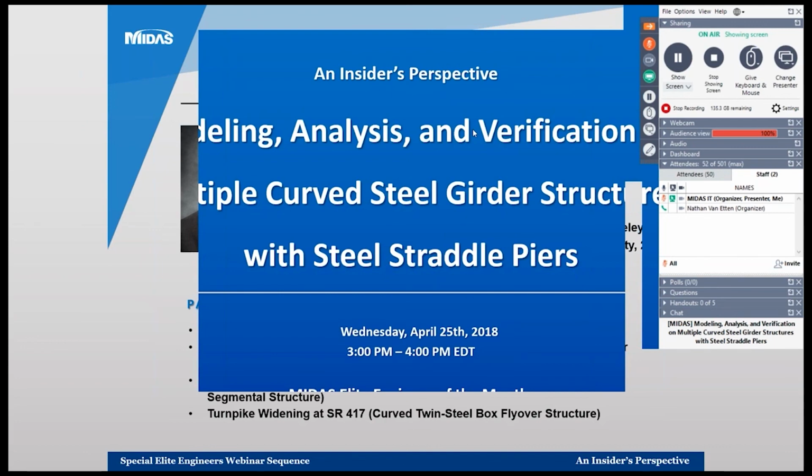When you have an elastomeric bearing pad, there's a lot of merit in accounting for that change in vertical stiffness, and MIDAS Civil can definitely handle that process. However, because in this case we're using disc bearings or pot bearings where the vertical displacement isn't very prevalent, especially under pure compression loading, we did not model the vertical stiffness of those two connections.